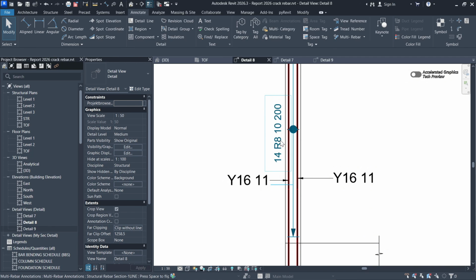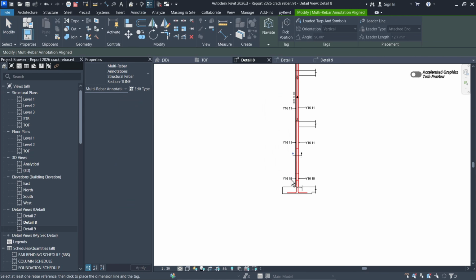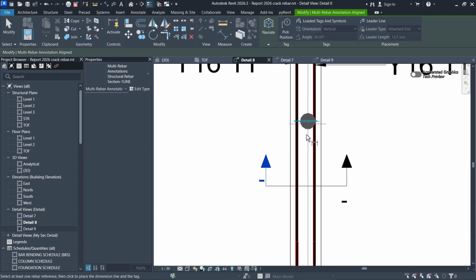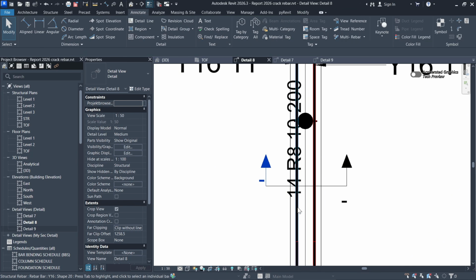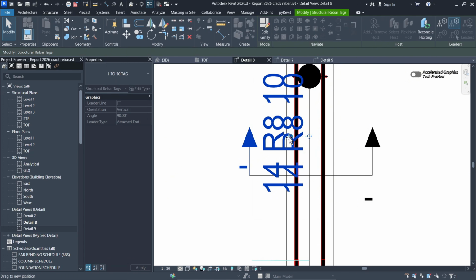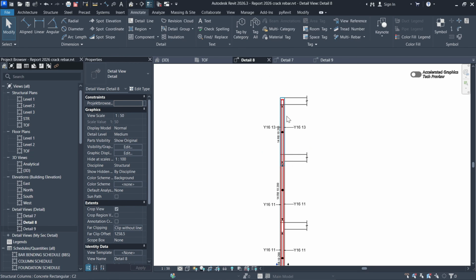Okay, so I'll also select on this one, CS on my keyboard, no leader, and I can pick it. Which one is remaining? This one. So you can see that it's quite repetitive, so I'll not even waste so much time doing too many things. Tab on your keyboard to select the tag and now move it somewhere here. So I think I'm happy with the column.